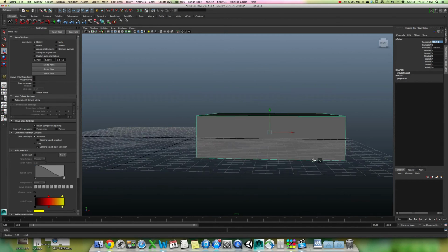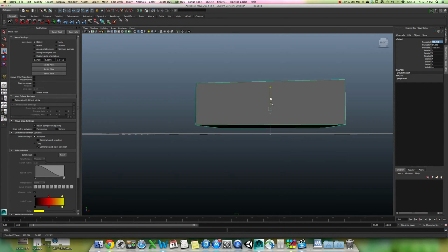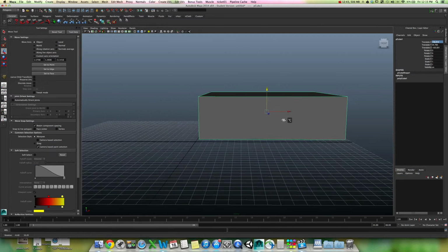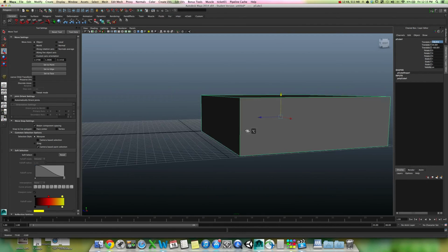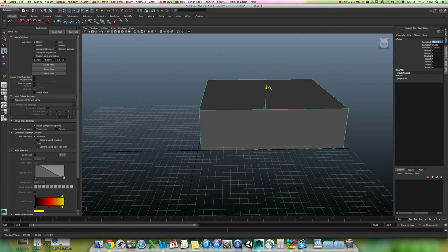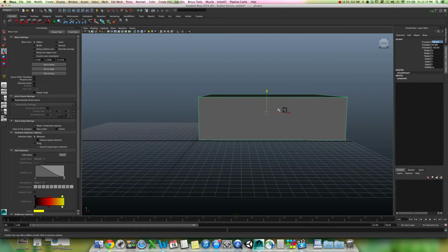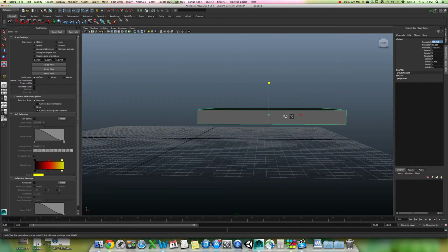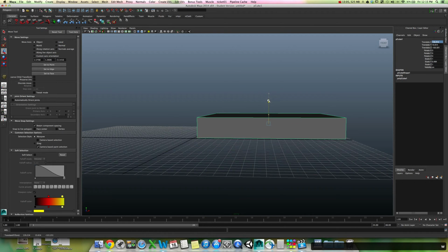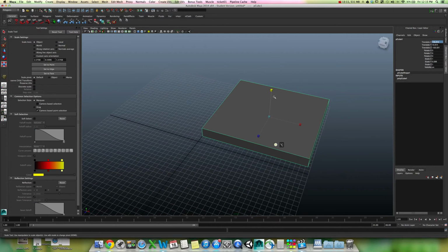All right, now the problem is this pivot point is in the center of my object. It's not very useful for aligning things. If I want to make a staircase, and this is the base of the staircase, I want it to align with the ground plane, which is 0y. And in order to do that, sure, I can kind of make it move up a little bit, and I can kind of eyeball it and say, well, it's close here. And then maybe I can scale it to make this a little smaller. But you see, everything's happening from this middle point, which is not really very useful for me. It's really hard to get this to set up right, and then I want to scale it some more, and I'm like, well, now it's scaling it from the middle point. It's not very handy or useful.